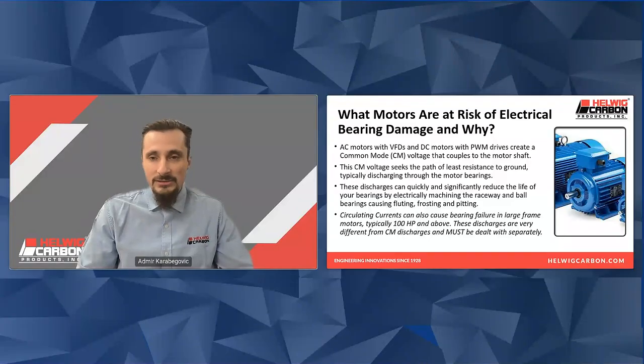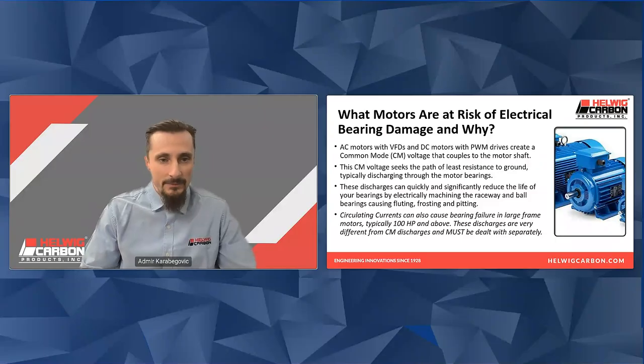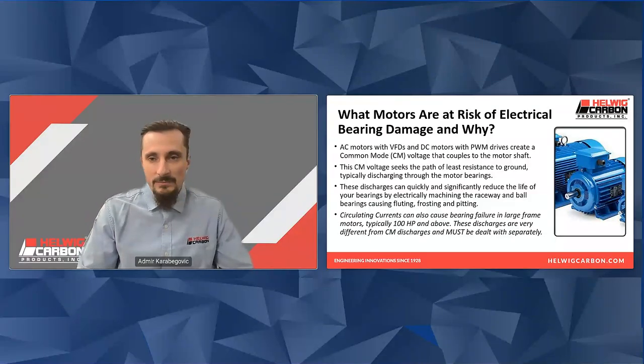Basically, we're electrically discharging, machining that raceway and ball bearing, causing fluting, frosting, and pitting. There is another problem called circulating currents that can also occur. That typically happens on larger frame motors. As motors get larger, the complexity of the motor design increases, and typically anything over 100 horsepower and above. These discharges are very different from common mode discharges and must be dealt with separately.